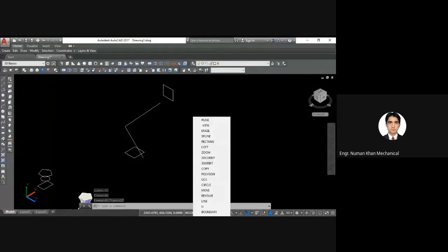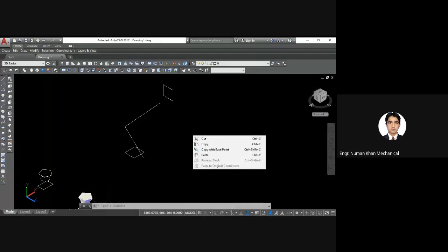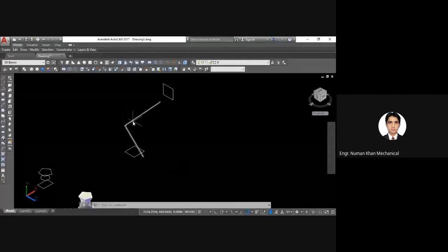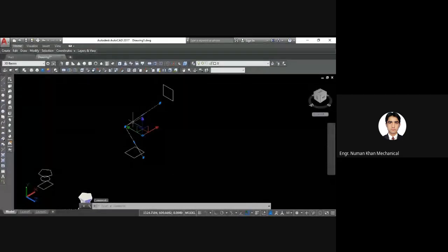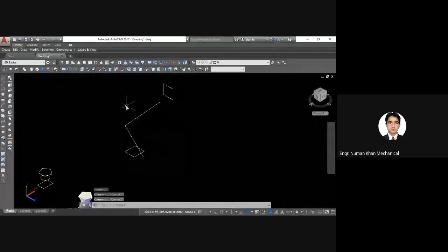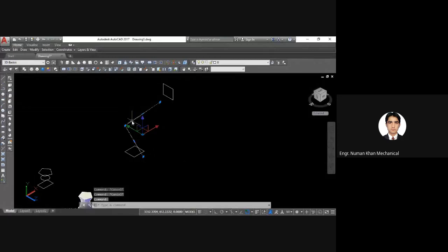This is the option. We can convert the polyline into curve fitting. We have an option over here with the help of which we can convert this polyline into curve fitting. I don't know why it's not working over here. Okay, let me change this one to spline. This is a spline for this conversion.